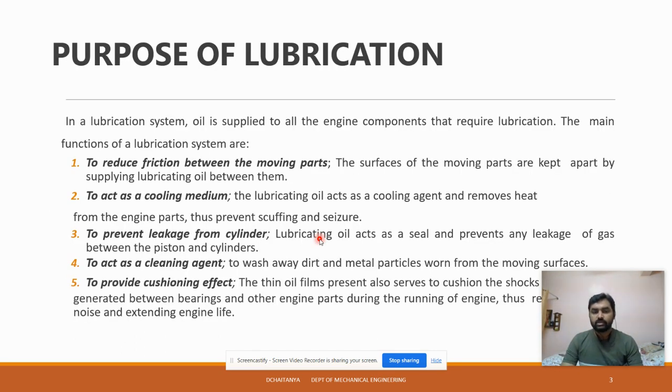So you can see what the purpose is. The first is to reduce friction between the moving parts, and as I said, it also acts as a cooling agent or cooling medium. And the main thing is to prevent leakage from cylinders. You all know that in unit number 2, we studied the different processes involved in internal combustion engines: the suction stroke, compression, expansion stroke, and exhaust stroke.